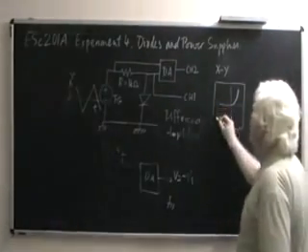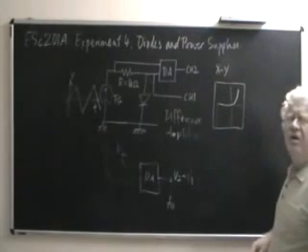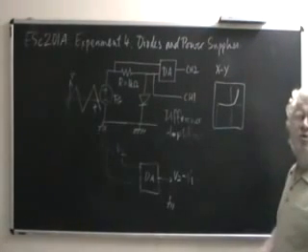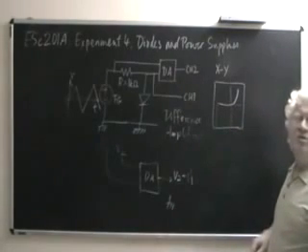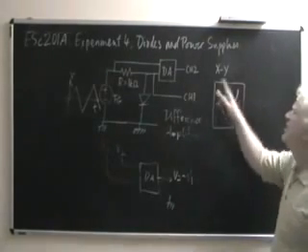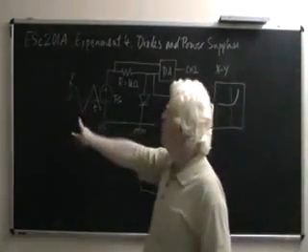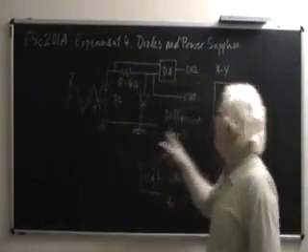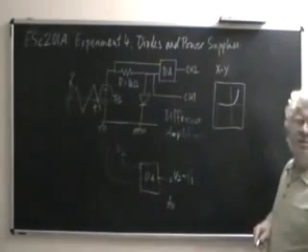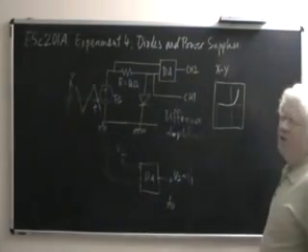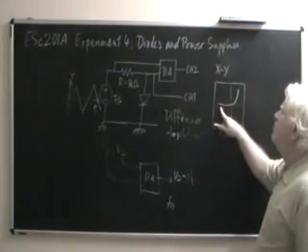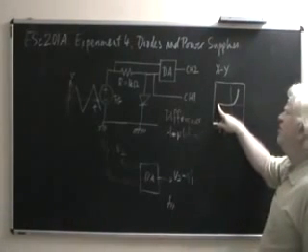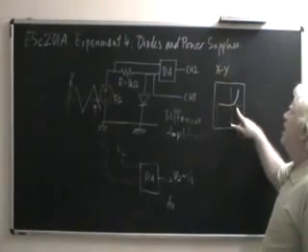You would not see this part because, as I said, that is a destructive process on the diode. You do not want to see that. It happens only once. And this is being done repeatedly because a sawtooth waveform is being applied to this circuit and it is generating this. So you cannot see the breakdown. You can only see the part before the peak inverse voltage, which is here, this part,